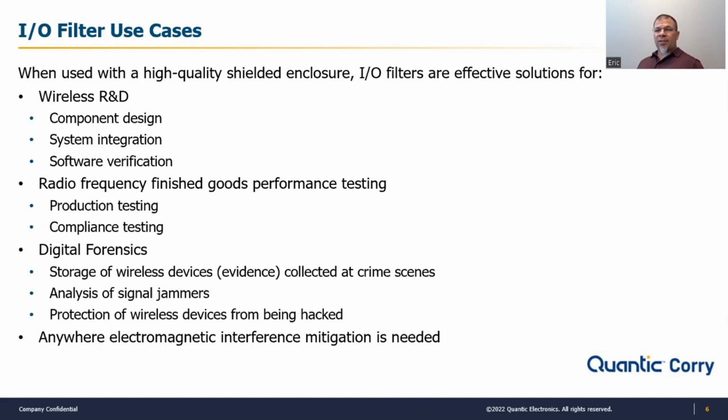That pass-through allows for the communication to flow through in both directions to the device inside the chamber and whatever device you may have outside the chamber. And so it's commonly used for debugging radio frequency components, the design of those things, being able to analyze them in a quiet environment and pass the data back and forth to those radio frequency components without affecting their operation.